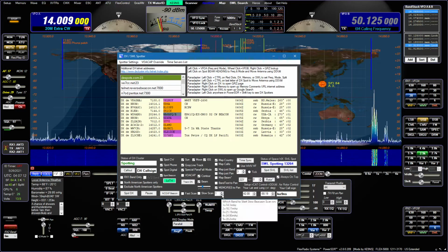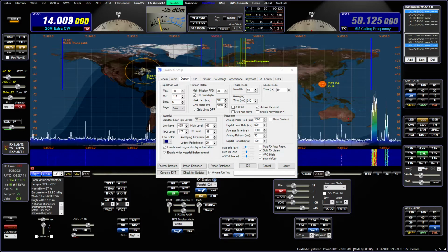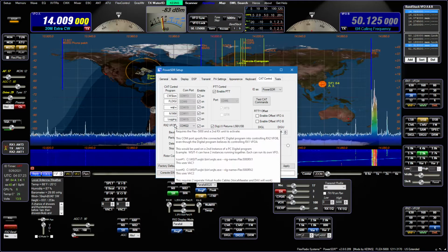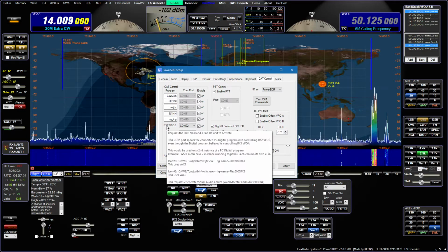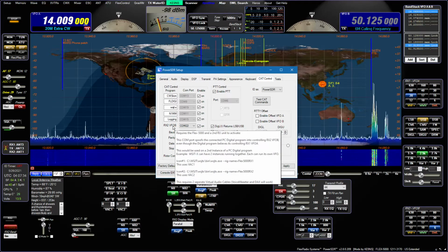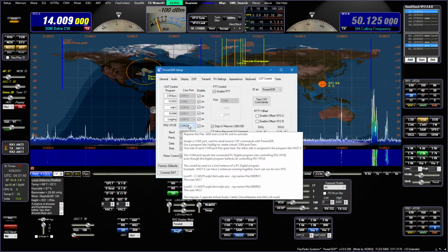The next is using RX2 for CAT. Okay, so I added right here this additional CAT control, and what that does is if you have a program like WSJTX FT8 and you want to run a second instance, which I describe on my webpage, if you do a virtual COM port pair, and in this case 23 is the other end of this COM port pair, so 23 is what WSJTX is set up for a second instance.